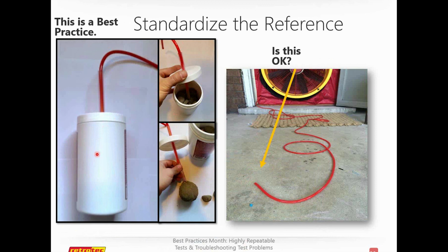Now, if your fan is going at 100% fan speed and you're still not getting any readings, that means that you need to open up that fan a little bit more, and that means take one of the range rings or plugs off. But that's a very good question, but a little bit more advanced than what we're talking about today. So let's move on.